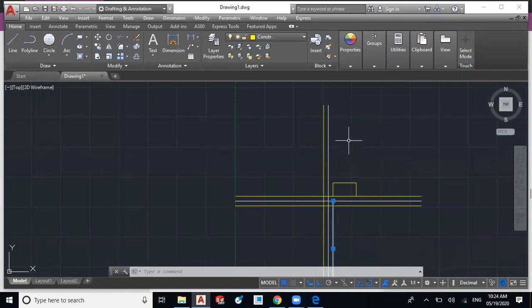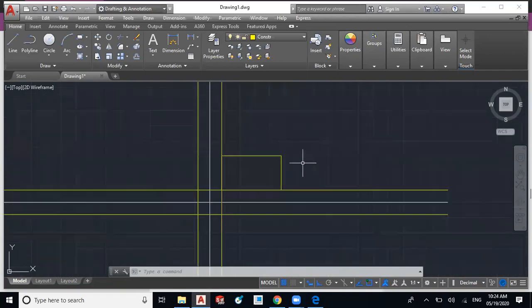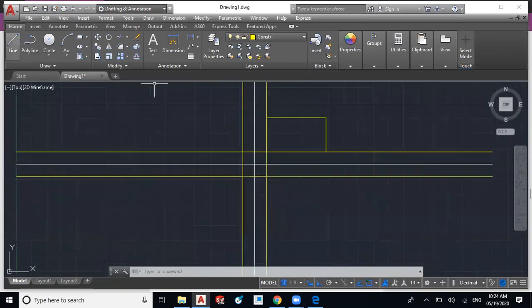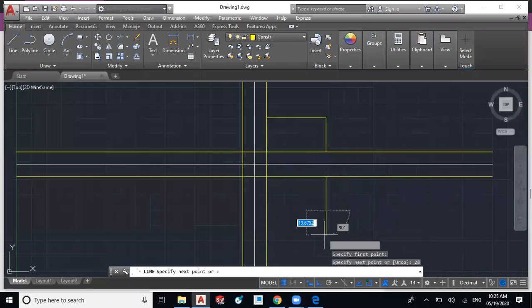Okay, we will see afterward how to reduce this length. Now we have drawn the box for front view, that is length of 50 mm and height of 28 mm. Again we have to draw the box for top view, that is we have to track this length point. Just go on the end point and track it down. You will get the intersection on the spacing line, yellow line. From that cross section you have to start. The width is 28 mm, then length perpendicular to this spacing line, you will get the 50 mm exactly.